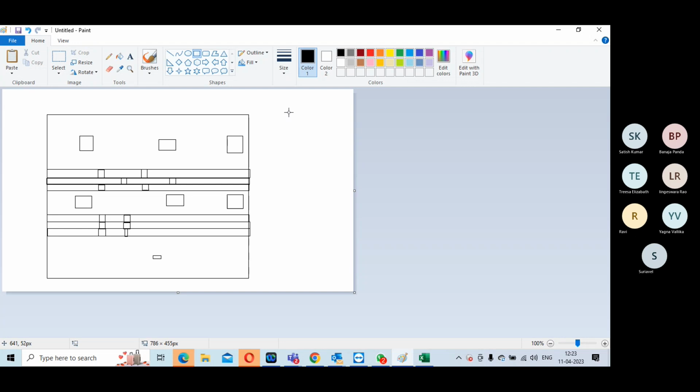For OR logic, the cell is an isolation cell, so that one of its inputs will always be tied to 0. So any change that happens to the other pin, the output will always be kept at 0. So any signal propagating from this off domain will not enter into the on domain. I mean, it will not reflect into the on domain. Similarly, for AND logic, the cells will be the isolation cells.